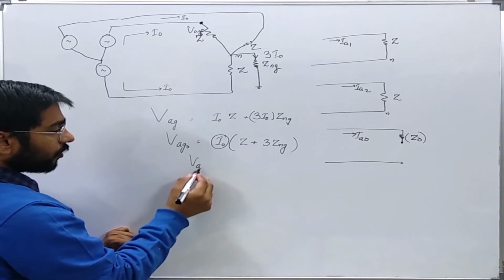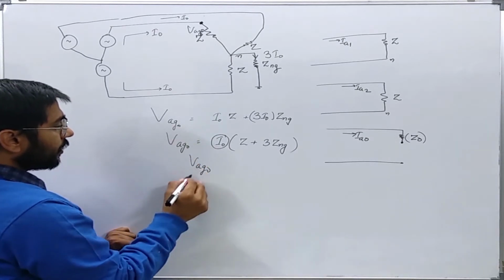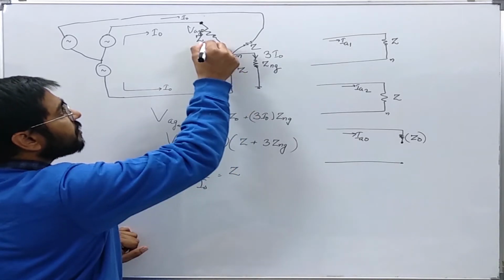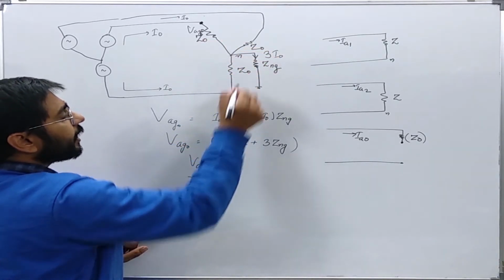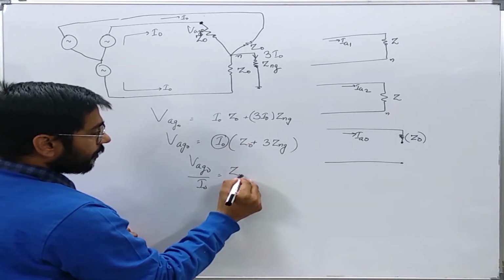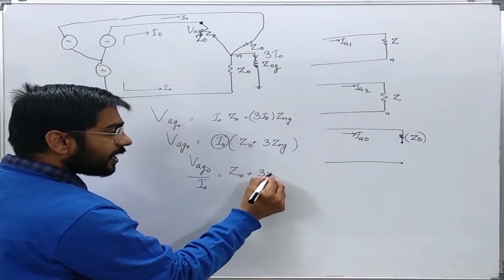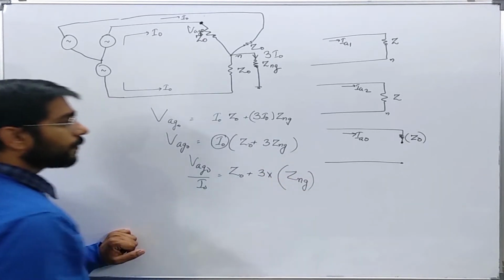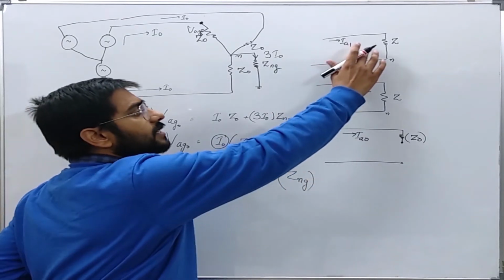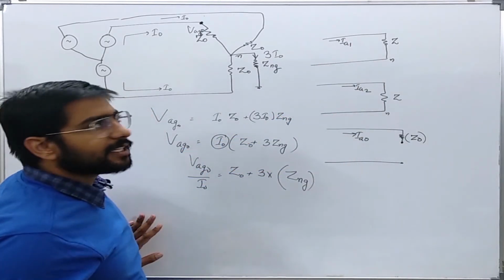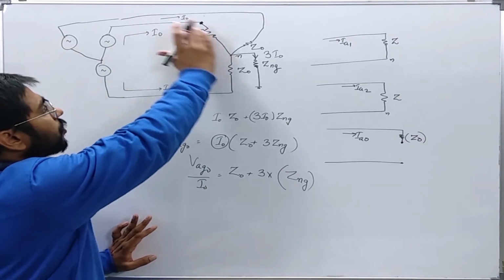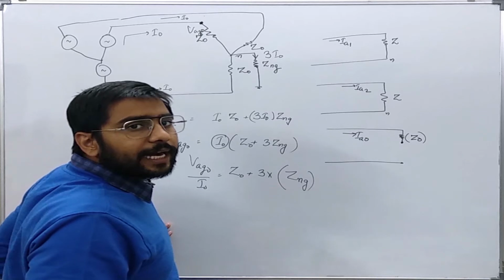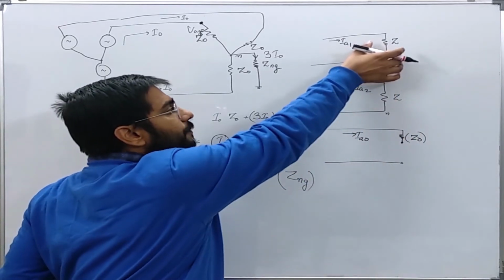The impedance offered to the zero sequence current is equal to the zero sequence impedance of the equipment plus 3 times any impedance connected between neutral and ground. The positive sequence and negative sequence networks will remain the same because it is a balanced system, so the per phase impedance seen by positive and negative sequence currents will be the same.